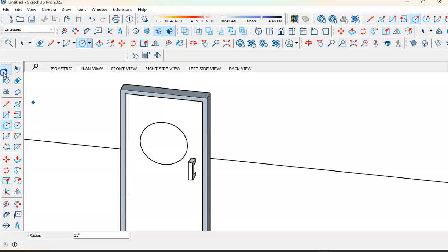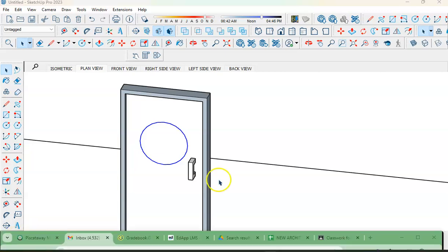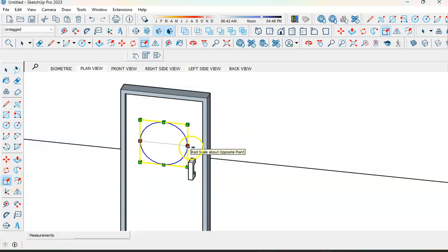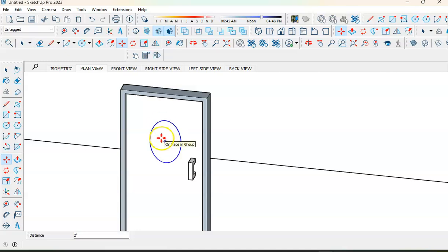How do I change the circle to a rectangle, oval? Circle to an ellipse? Anyone? No one? You'll use the scale command, right? And I'll just do this. See? Boom. Fairly easy. And then I can put this in the center. And I'll move it up.